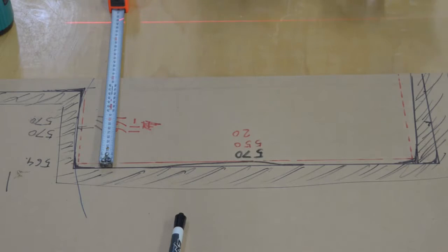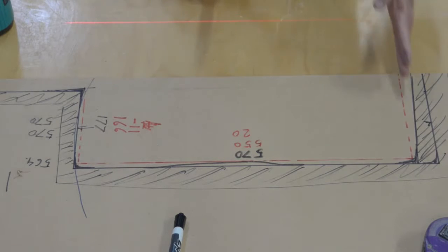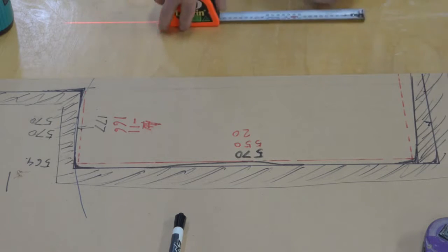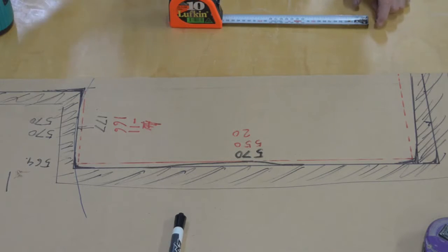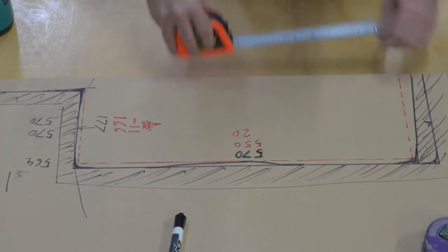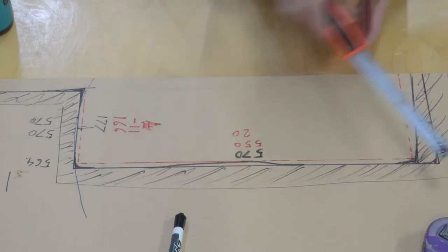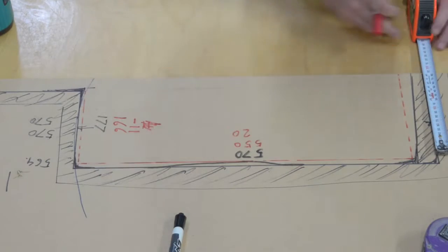Now as for testing something for square, there's a couple of different ways you can do it, but there is all sorts of scope for variations and tricks being played on you. But a good method, and the Egyptians were the first to use this method that I'm aware of. Many believe they didn't know quite why, but they used a 3, 4, 5 triangle. Now if you need to learn about Pythagoras, that's somewhere else.